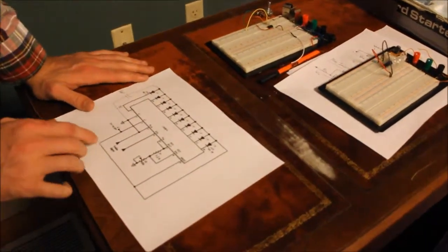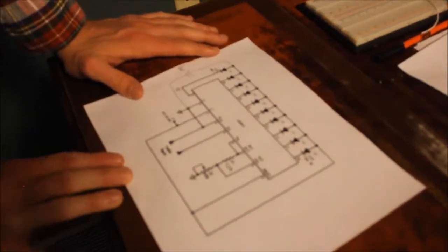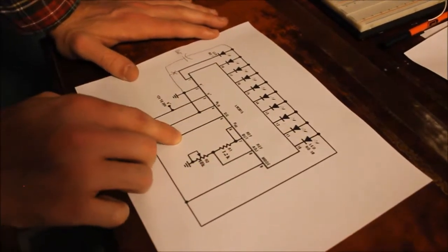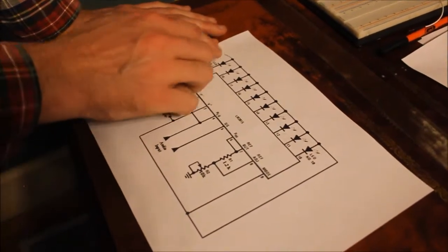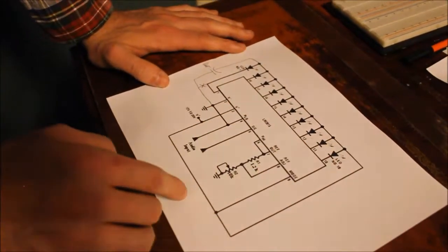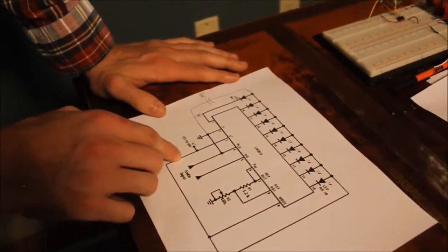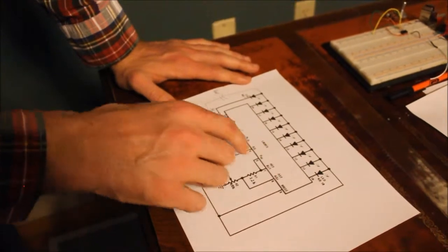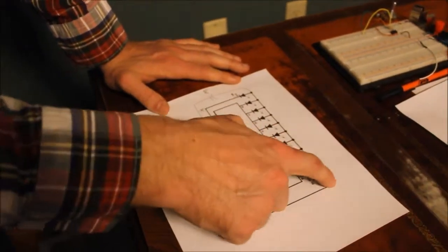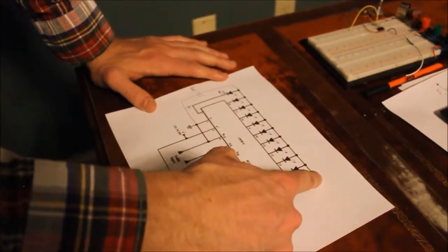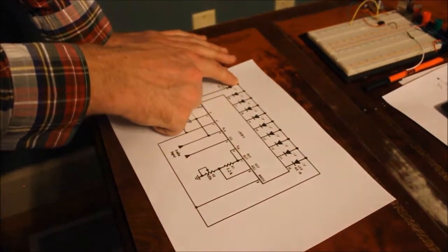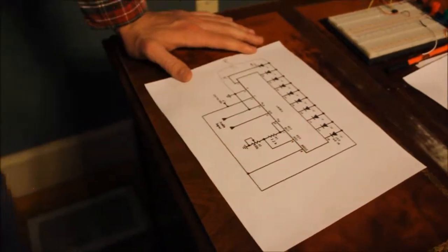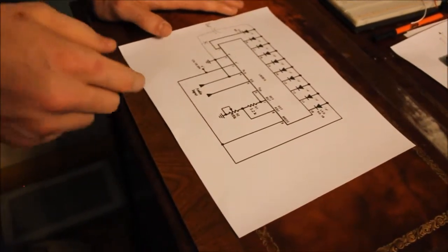This is the schematic of what the VU meter is. Essentially, this left to right signal will be your signal in at pin 5. The idea behind this is you have 10 LEDs lined up. You have this positive reference voltage here that goes in at pin 3, but it also loops around to the top, parallel with all these lights and the mode. Putting the positive voltage into the mode puts it in bar mode instead of dot mode.